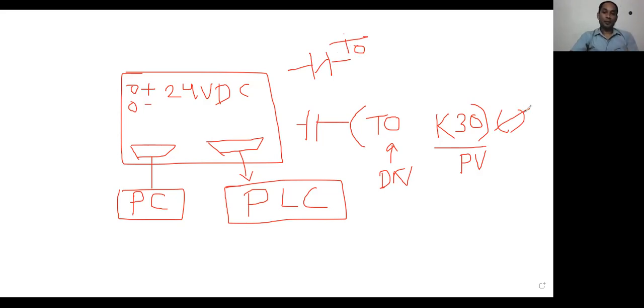In the previous program, you have seen I have taken M1, M2, M3. Instead of taking M1, M2, and M3, in Mitsubishi, you can use the timer address directly. Accumulator, the running value ET, is also T0. When the timer runs, it will show you the running value here. So T0 is its accumulator also. Preset value and accumulator, these two are required for timer, for HMI and SCADA.